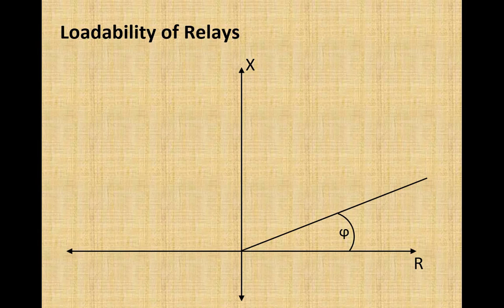When we say that load is increasing, it means power in MVA as well as current in ampere are both increasing. Power and current increase due to reduction in impedance if we keep the voltage fixed. So as impedance is decreasing, that means our load is increasing.